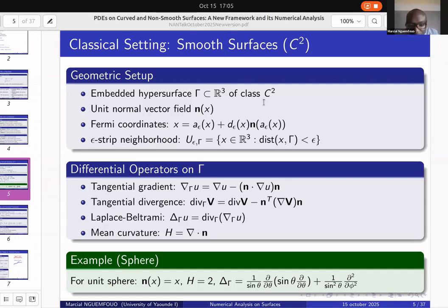Because in the numerical simulation, when the triangles are skinny, they can cause instability. To have a good triangulation, they use Delaunay triangulation, which makes the triangles close to equilateral to avoid skinny triangles.